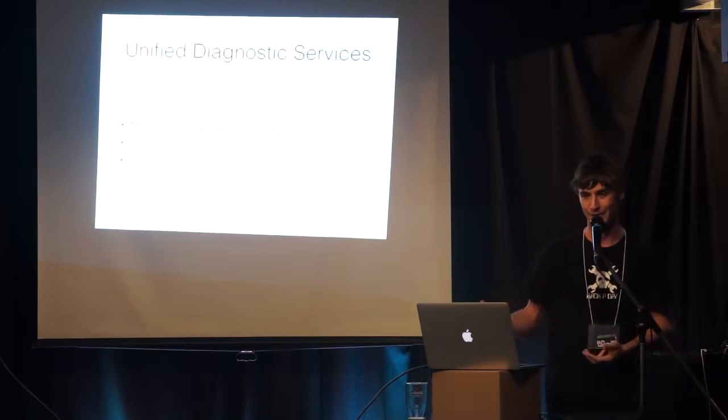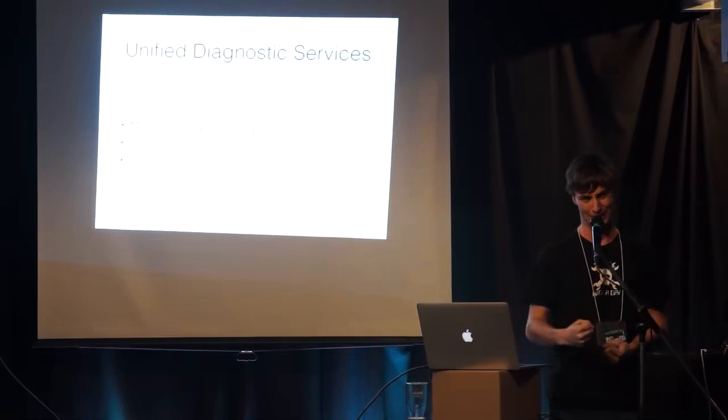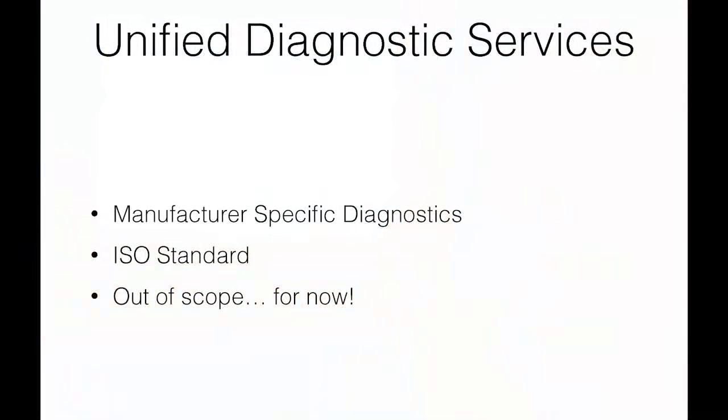Beyond OBD2, it's very basic, minimal. You can read stuff. You can't do much. Unified Diagnostic Services is how you do things. This is what the manufacturers use for their own diagnostics, and it's actually an ISO standard. Unfortunately, standard used loosely. The standard defines how the communications work, but then there are manufacturer-specific codes for everything. So you kind of have to know how to navigate those codes.